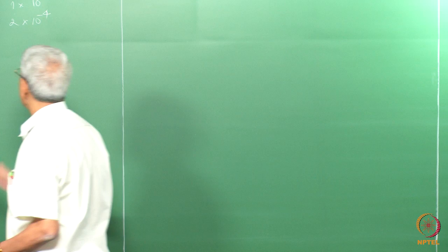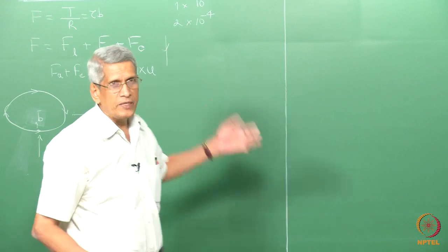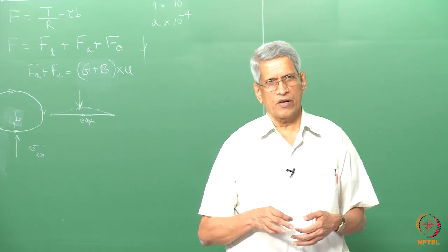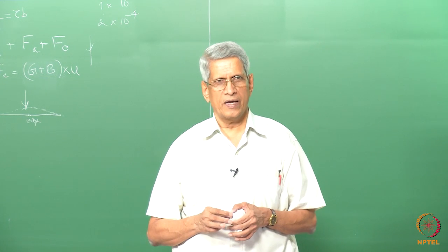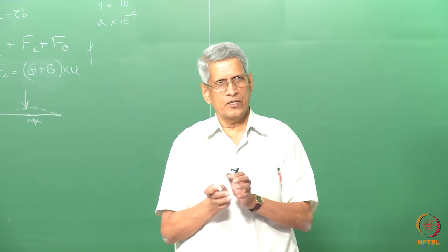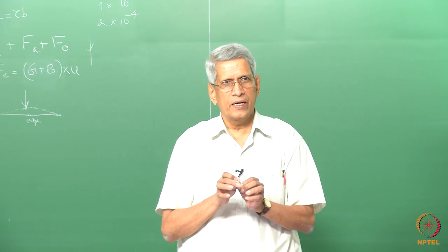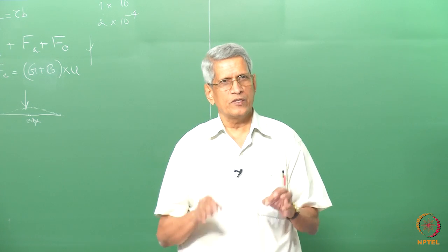As the sample is being quenched, many of these vacancies, when they are mobile, try to come to the surface and equilibrate. And beyond a particular point, when this cannot happen, these vacancies which are close by a short distance can agglomerate and form vacancy loops in the material.